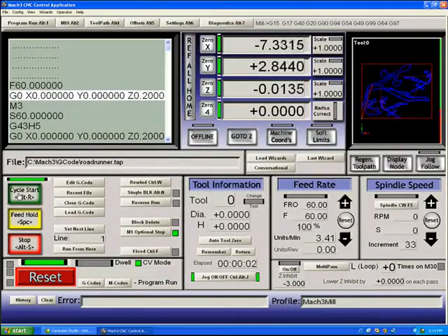When I hit cycle start to start the program, it will begin to move, and you can see that my speeds and feeds are probably not adjusted appropriately for this particular program, but eventually you'll see a green line trace out the path of the Roadrunner, and your motors should now be feeding themselves at that speed in that area.